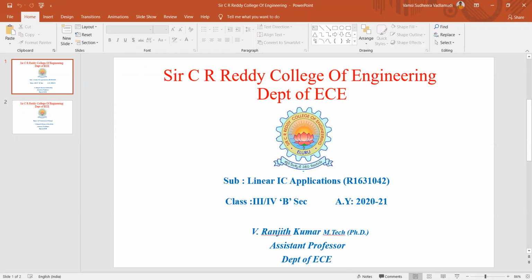For the non-inverting input, I'm taking a reference voltage, which I consider as V level, the voltage across R2. Here I'm giving plus VCC, the positive power supply, to my potential divider network. The voltage across R2 is taken as V reference, which I consider as V level.